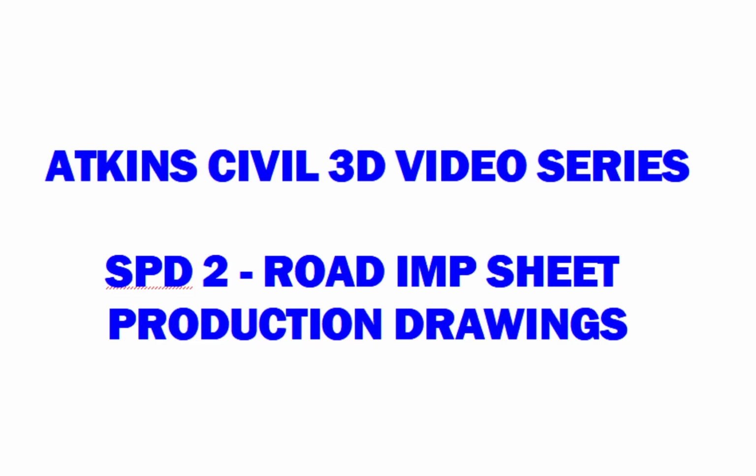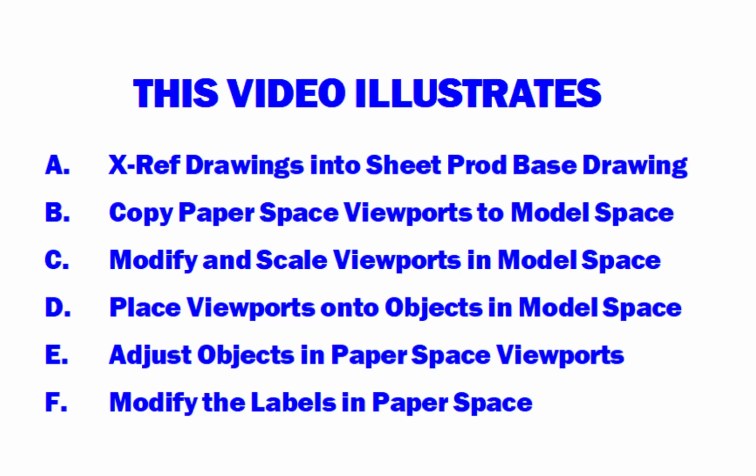Atkins Civil 3D Video Series, SPD2, Road Improvement Sheet Production Drawings. This video illustrates: A. XREF drawings into sheet production base drawing. B. Copy paper space viewports to model space. C. Modify and scale viewports in model space. D. Place viewports onto objects in model space. E. Adjust objects in paper space viewports. And F. Modify the labels in paper space.